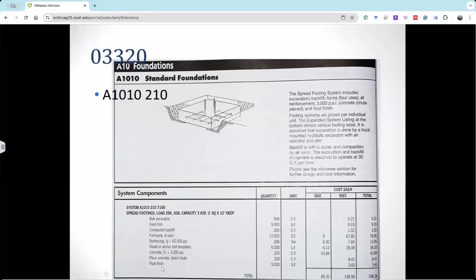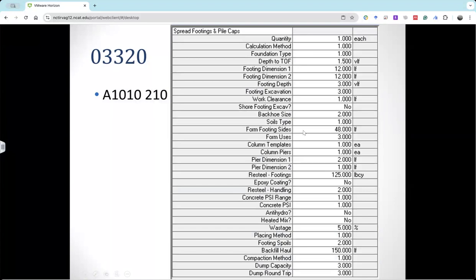So you can check here. The square footage is 9. And you see the volume for your concrete is here. You use 9 divided by 27 because you want to get cubic yards. So you are getting 0.33. Does that make sense? I think you already did this kind of calculation in your CM course 233. And I think right now they have changed the name to 333, right? Whatever. That's meeting 1. Okay, so those are the detailed information.